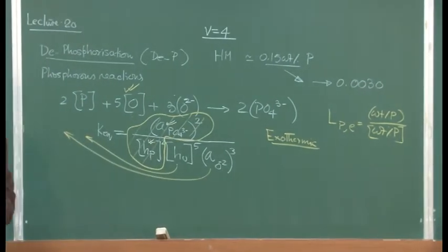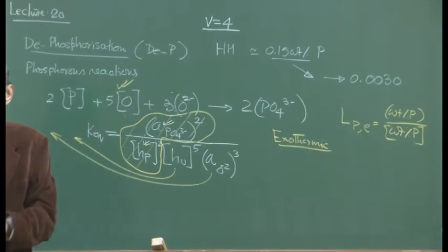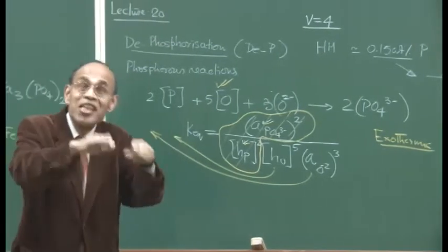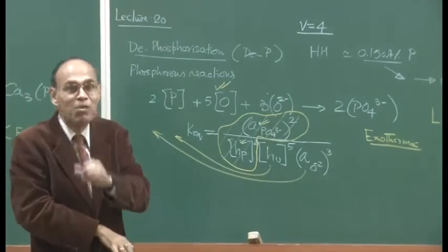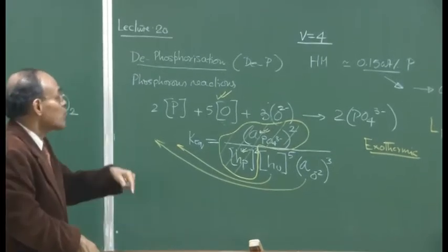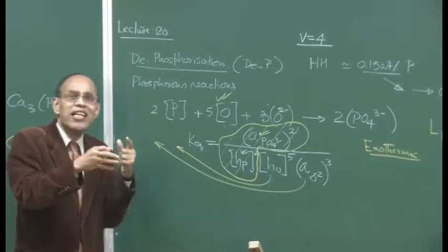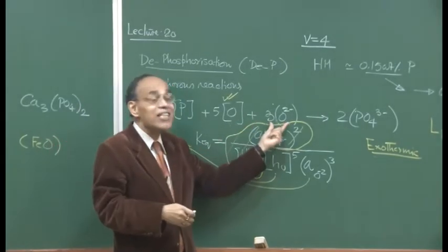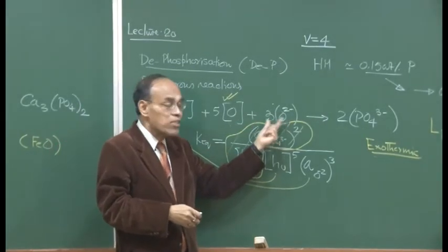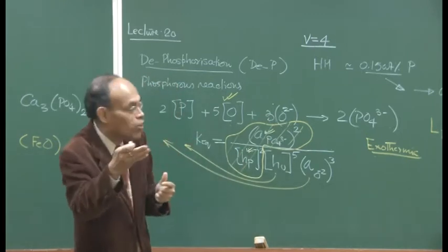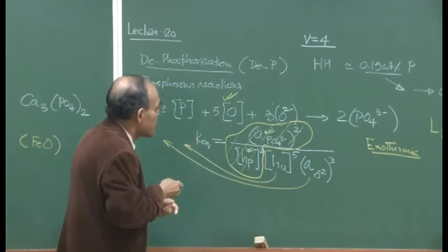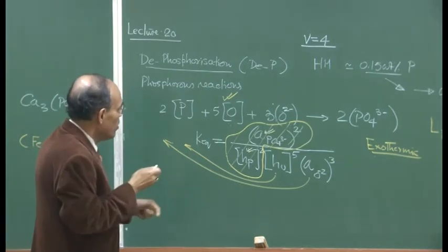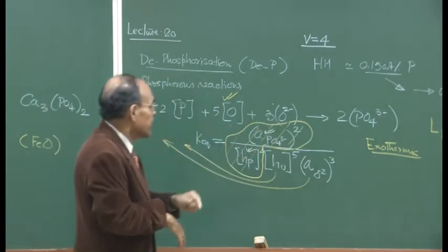and this is called the phenomenon of phosphorus reversion, which is not a problem during the initial stages of steelmaking. That point must be understood very clearly, because in the initial stages phosphorus is also not removed to a significant extent. In the initial stage it takes half a minute or so, then the phosphorus removal starts to occur in the system itself.